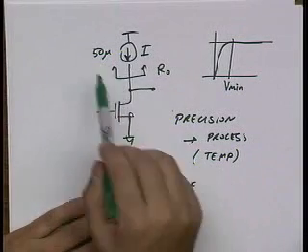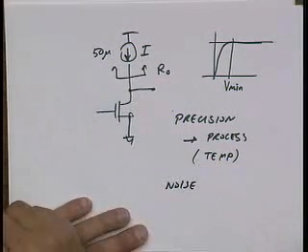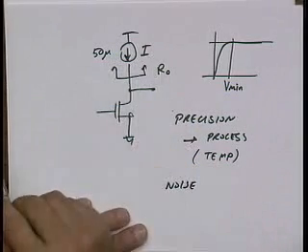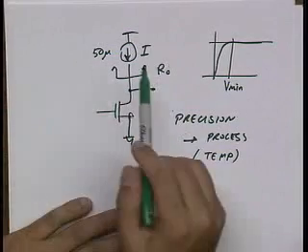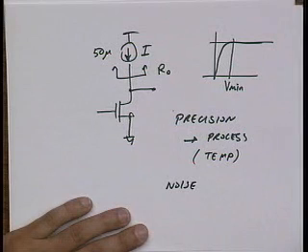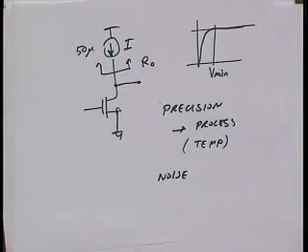You looked at a PMOS current source and figured out how much noise it added to the overall circuit. You found there's a direct trade-off between the noise of the PMOS device and the swing. You have to make the V star large to get low noise, but that directly eats into your swing. Okay? All right. So that's about right. Those are the things that we care about.